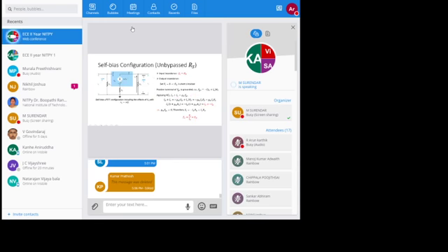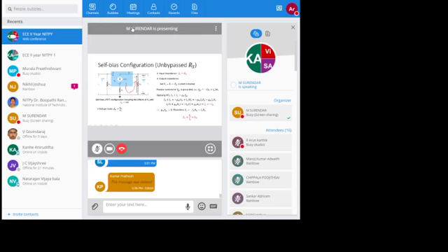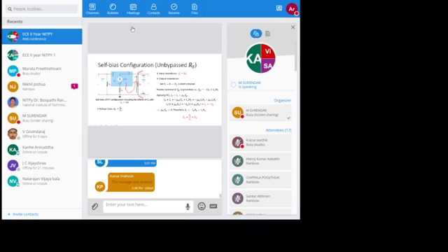For voltage gain, we need output voltage by input voltage. Firstly, the output voltage: this GM into VGS is flowing through this resistor RD. So the voltage across this RD is nothing but V output. So we have RD into GM into VGS as output voltage.